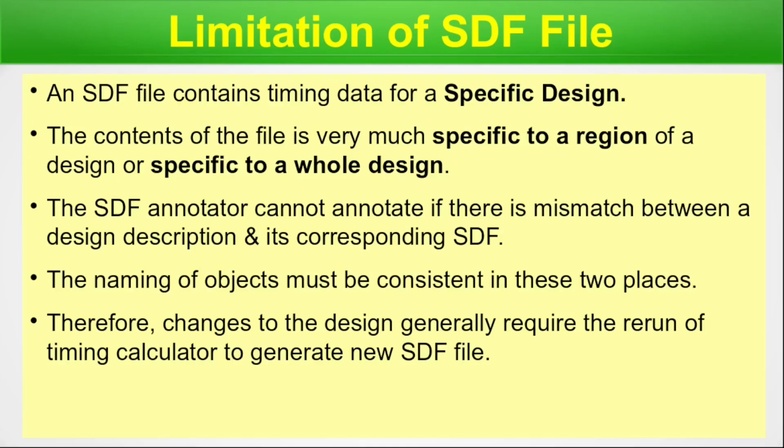Inside the design, if you have changed something, maybe its hierarchy, maybe some addition, some subtraction, anything, or maybe renaming of any port or anything like that, those things cannot automatically come inside the SDF. The SDF has to be manually generated by the user.